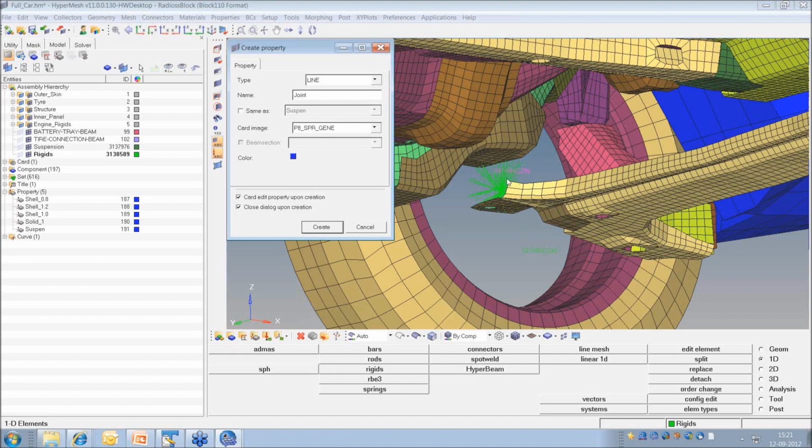And the other differentiation is all other springs follow their own local coordinate system. So node 1 to node 2 will always be x in the case of other springs, except here in type 8, by default it follows the global coordinate system. You have an option to select this cube, that is a different thing, but by default type 8 will work in the global coordinate system.